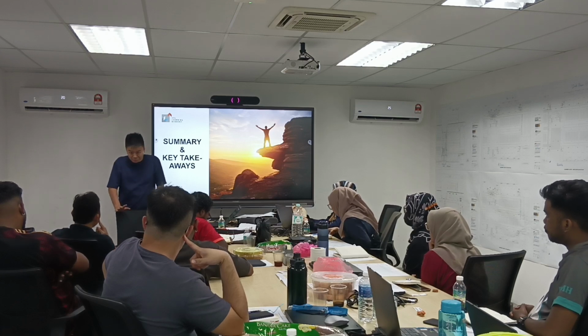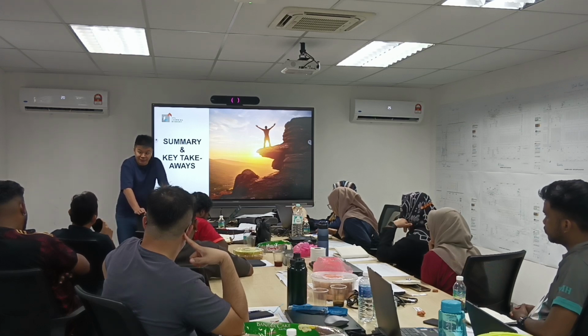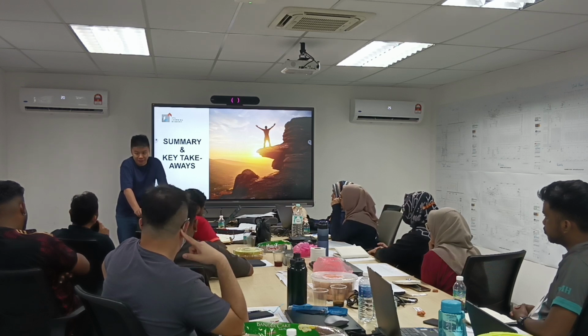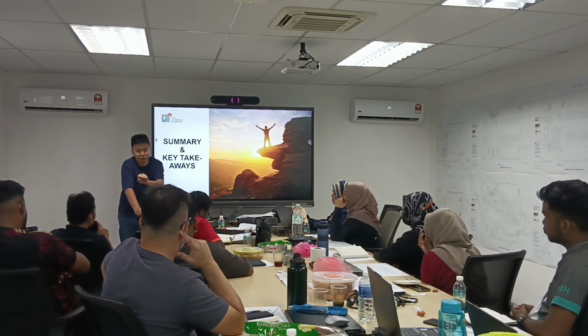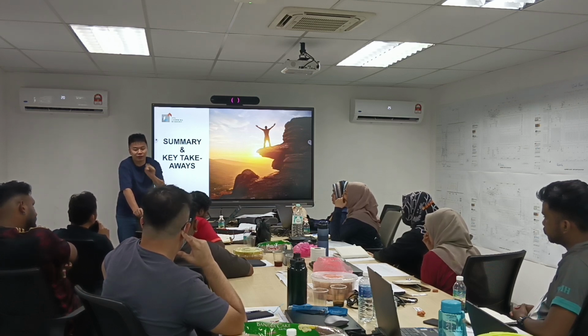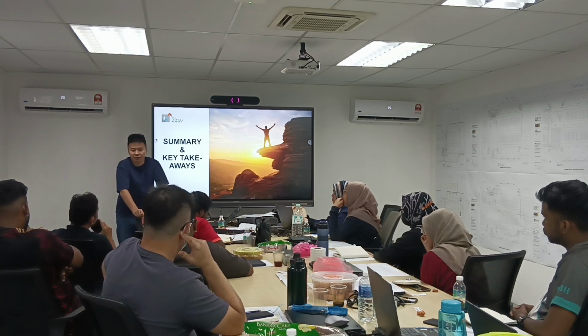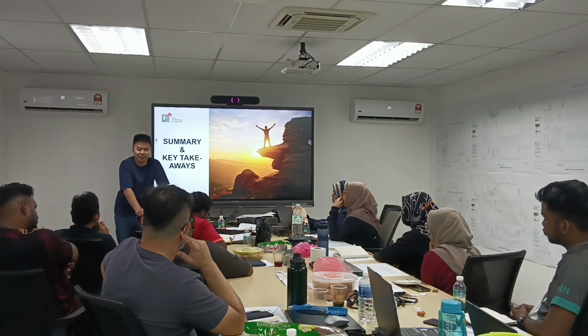So if you follow the PAM standard, upon project completion, meaning the CPC issuance, you shall disburse 2.5% because you're holding 5% retention sum. So they can only claim until 95. Upon you issue CPC, you give them 2.5. Then upon you issue CMGD, you give them another 2.5. Means 100% clear, if you follow the PAM contract. But if you follow the YTL standard contract, I'm not giving you anything until you finish your CMGD.